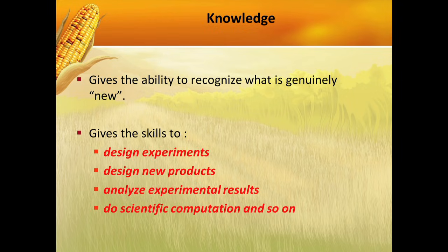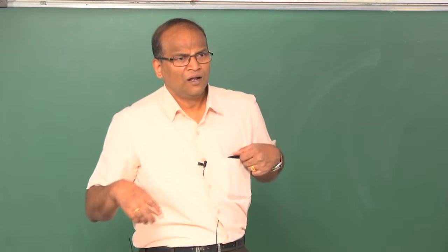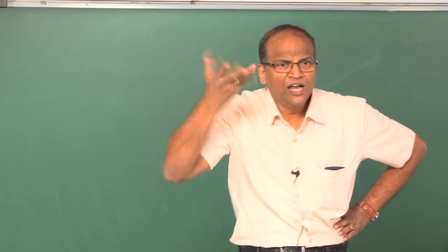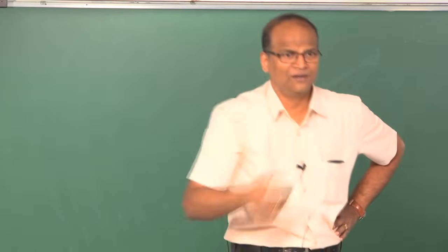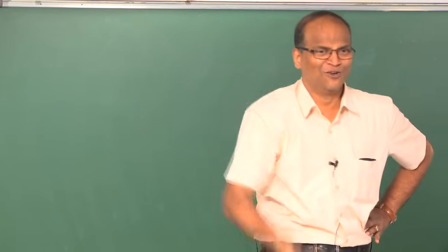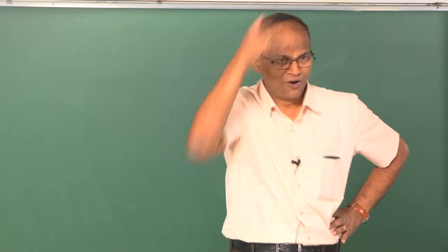It also gives you the skills to design experiments, design new products, okay. How do you design an experiment? How do you measure a temperature of 500 degrees centigrade? You may have a lot of ideas. You remember how to measure temperature: when I went to the clinic, the doctor put a mercury in glass thermometer in my mouth. So you think you got some brilliant idea: I will use this mercury in glass thermometer to measure the temperature of a liquid which is at 500 degrees. Your brilliance will not let you know how to measure temperature. You should have knowledge. You should have a platinum resistance thermometer, or if it is a surface, you will use infrared. Therefore, you must know what other people have done. You should have knowledge. Creativity is one thing, but knowledge is very important, okay.